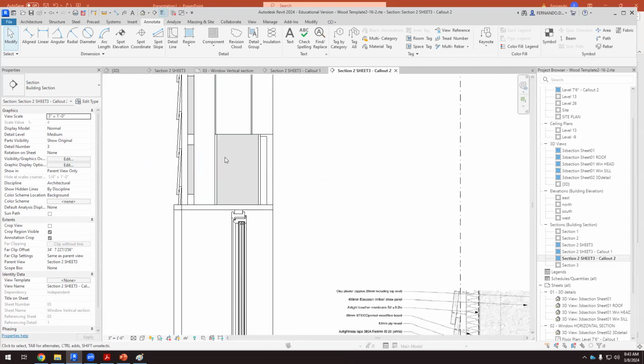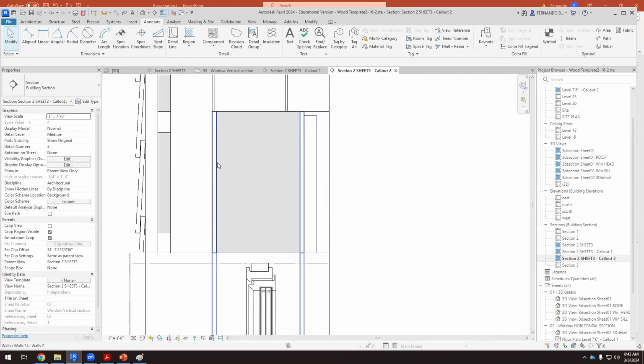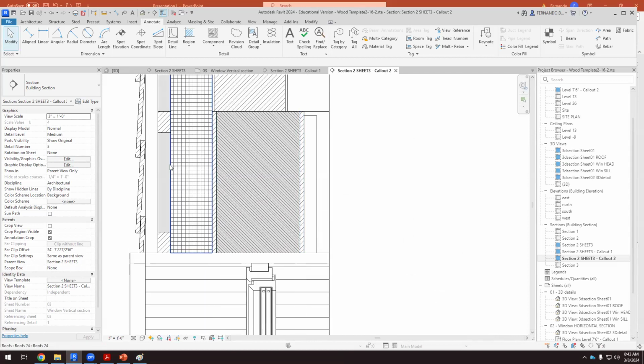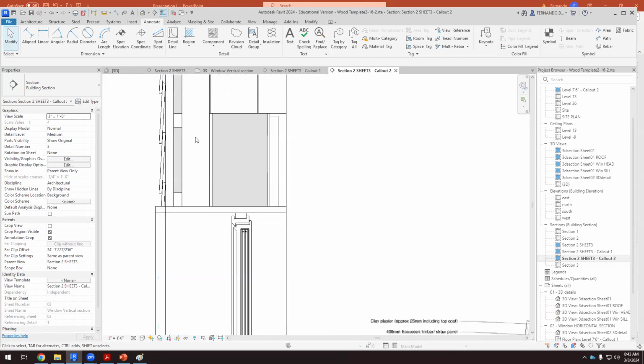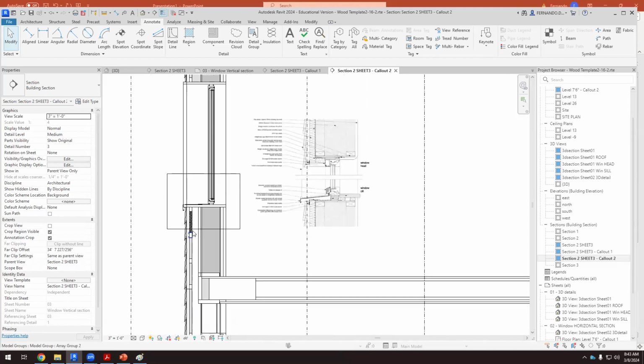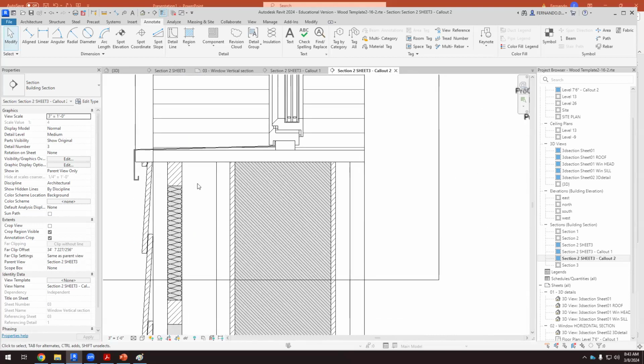With thermal insulation. So here we have the insulation. This is the OSB board. And here we have more thermal insulation. And then I have an extra layer of thermal insulation. The more, the better. So I'm going to use thermal insulation here. And I'm going to do a different thing. I'm going to use, in this case, a filled region.